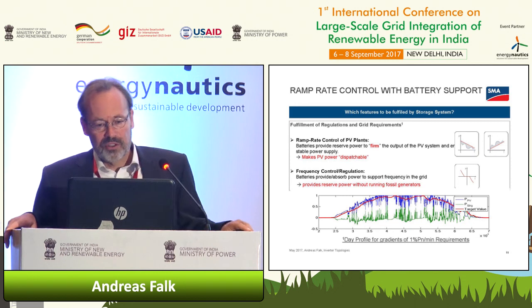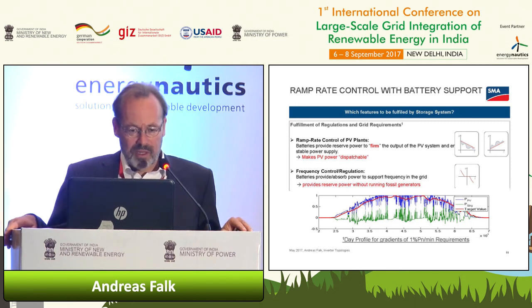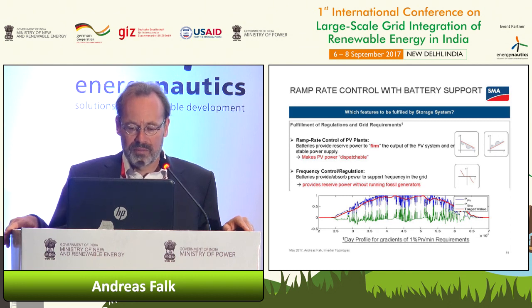And the ramp rate control, in that case, the ramp rate is limited to 1% of nominal power per minute.